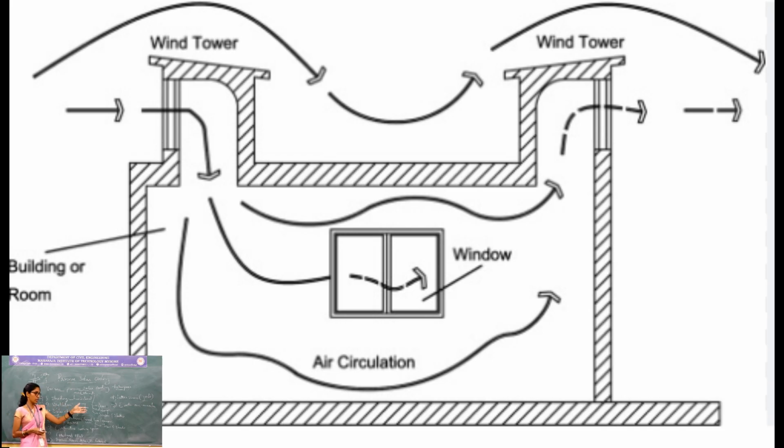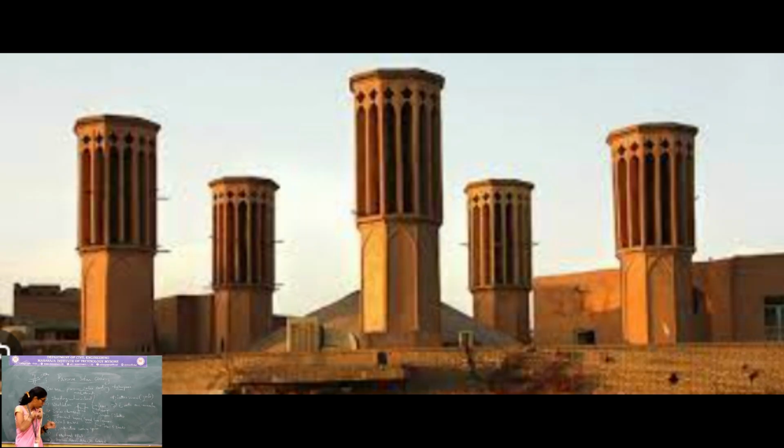So in the image which has popped up, you can see how the wind movement is going to take place, how exactly the wind towers are being constructed, and how the openings are present in your wind towers, which is going to facilitate the capturing. So here the capturing of the wind is happening, not the capturing of the heat, right? So it is the wind which is being captured.